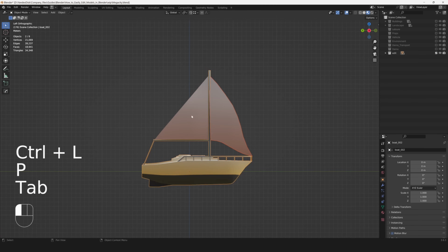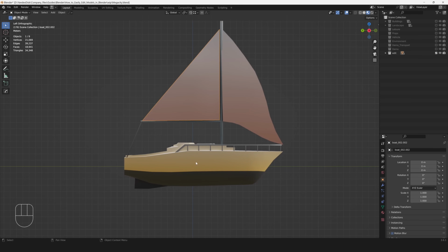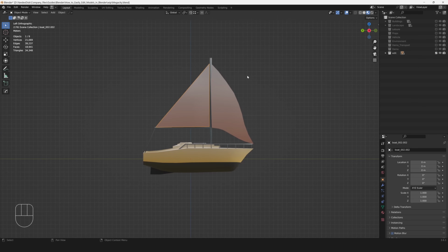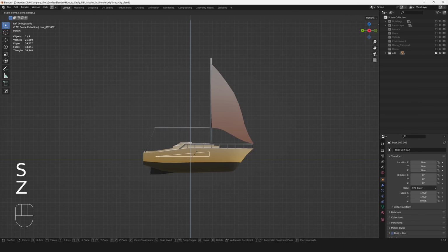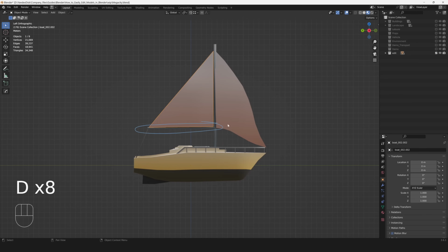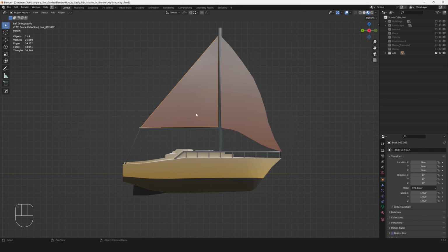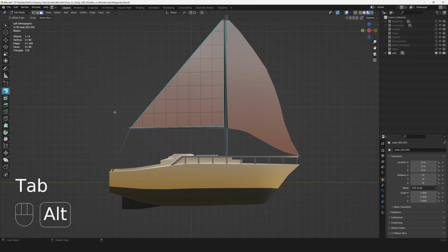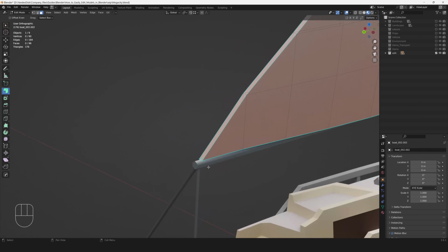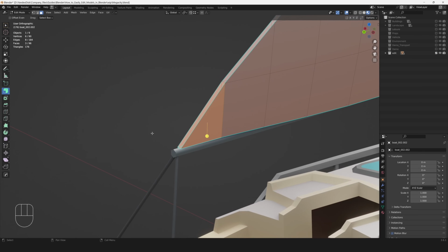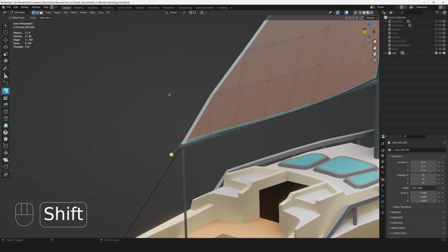My animation in Unity will be based on scaling, but there are some problems with object centers, so we should fix our pivots. We have a different video which tells you how you can solve these problems in different situations, but now I will just show you how you can quickly solve it here. In edit mode we should select these 2 vertices and place our 3D cursor at this position.